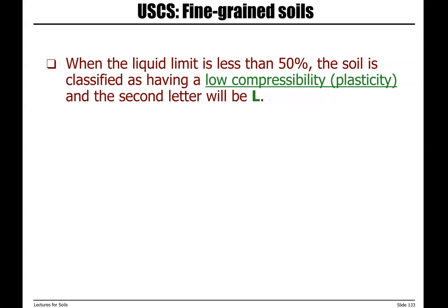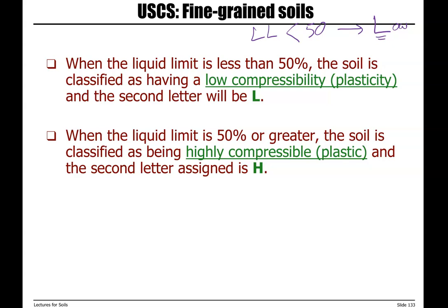So the next step for us is to check the plasticity. If liquid limit is less than 50%, then we have low plasticity, and we will use letter L. And if liquid limit is equal or more than 50%, then it means that we have material with high plasticity, and we will use letter H.